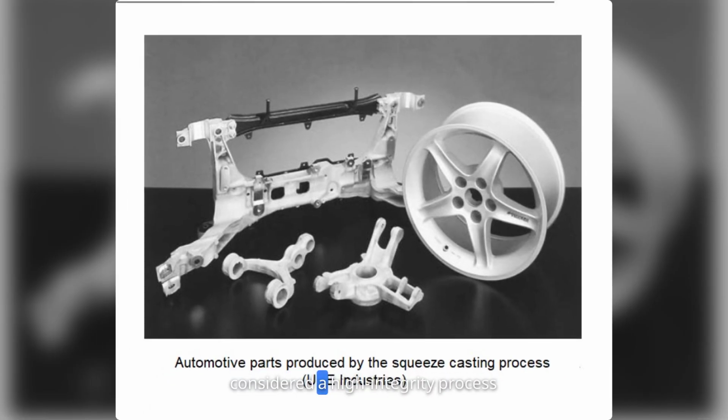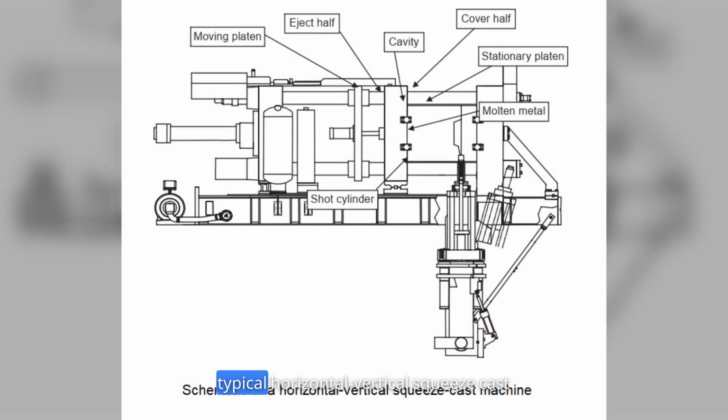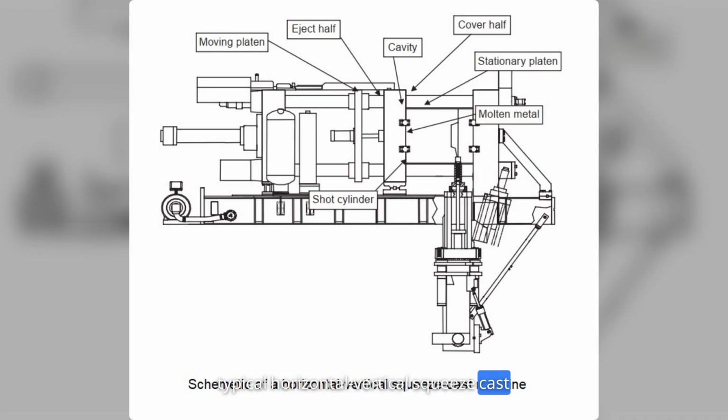Squeeze casting is considered a high-integrity process and has emerged as an alternative to conventional casting techniques: gravity permanent mold, low-pressure permanent mold, sand casting, and forging. Squeeze casting builds on conventional, high-pressure, high-velocity die casting practices and has been widely used to manufacture aluminium automotive components requiring high impact strength, high fatigue strength, and pressure tightness or wear resistance. This figure shows a typical horizontal-vertical squeeze cast machine.